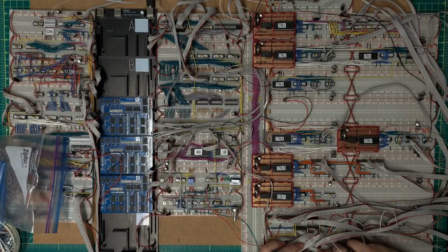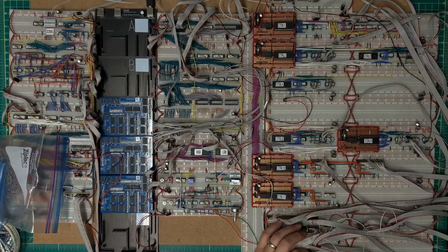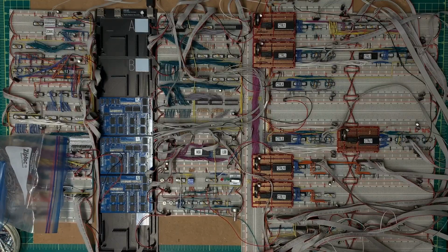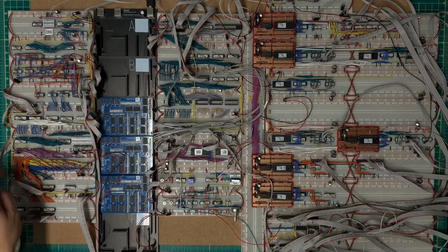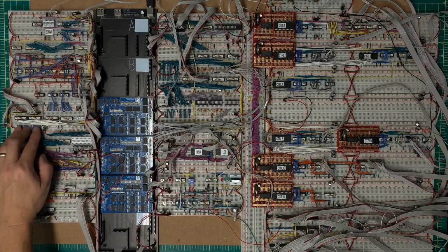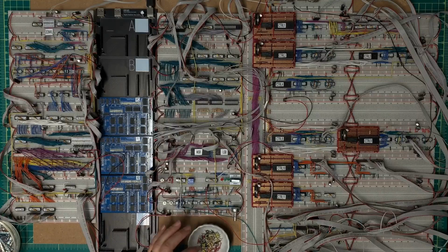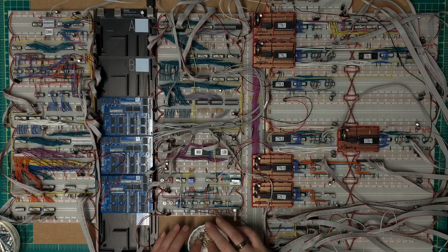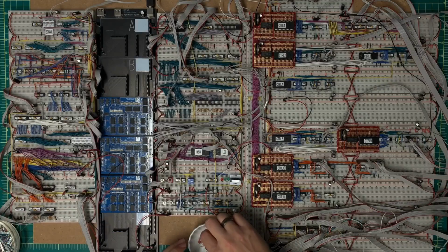Okay, and the final connection is to hook up the actual latch. Next in line is the invert, which I've got tied low. The next 2 in line are carry select, the 2 bits associated with that. I've already got those wired up, so I don't need to worry about that. The next 2 are going to be the select that is used over here on this end to select what is actually asserting out onto the ALU bus up here in blue. Right now, since I have nothing else, I'm going to tie that to 0, 1, and 0, 1 should be, or is, output 1 here. So let me get that tied quickly.